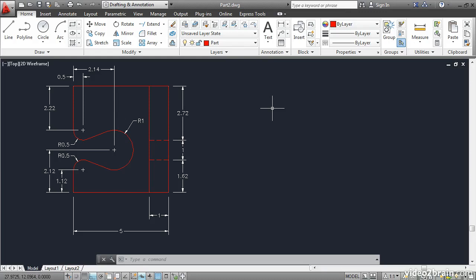Here we will explore the many ways you can use Object Snap with the project of drawing a mechanical part. Object Snap allows you to connect objects to the geometric features of other objects, irrespective of coordinate systems or regular spatial increments. Object Snap is one of the most important concepts in AutoCAD that, once mastered, allows you to draw with precision. Go ahead and open the Part 2 project file, and then click the Line tool on the Draw